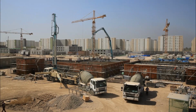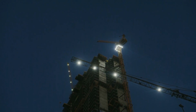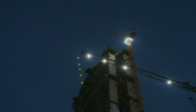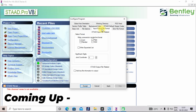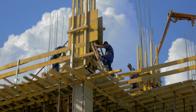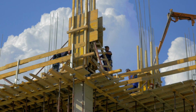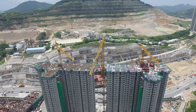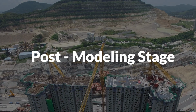So I will be taking a real-life project and show you the various steps involved in designing and analyzing a project in STAAD Pro. The complete workflow for the series will be the basic setting, then the complete geometry, then the model loading part, then the structural analysis part, then the concrete design, and finally the result detailing. I have broken all these topics into 3 parts just for you to digest it better. They are the pre-modeling stage, the modeling stage, and the post-modeling stage.